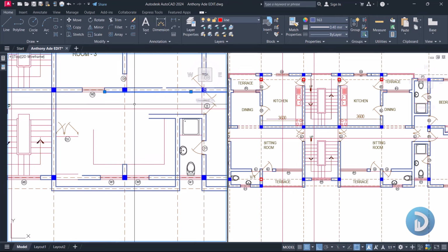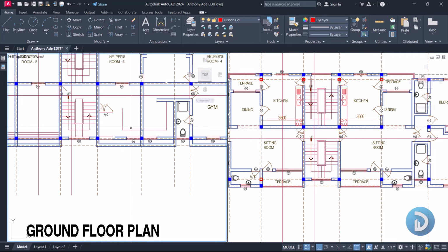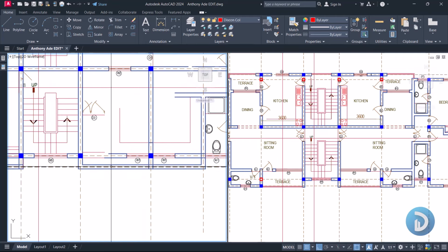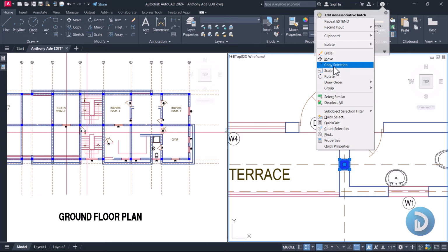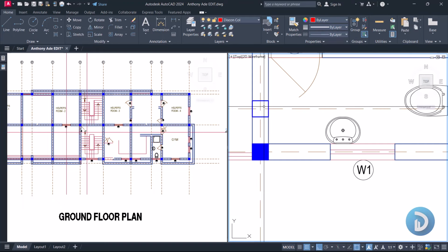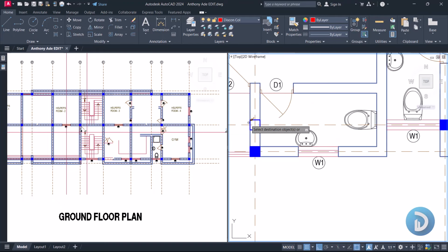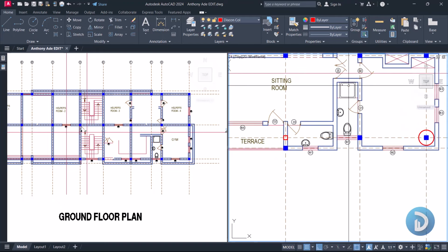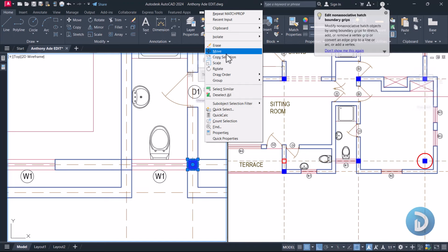and we'll extend this to this part, and we also extend to this part. Okay, so we'll have here as a panel, and this part will be a cantilever. Let's also take note that this column will also move from here to here, and will also be a discontinuous column. Okay, so we'll move to this part as well, and we reintroduce a new column for this cantilever.